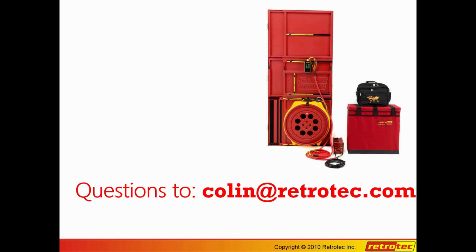Robert Ennis was asking, is it reasonable and acceptable to measure lower leakage area in a room that does not have a suspended ceiling but does have leakage points positioned above the required protection height? There is a thing that we can do, called a leak audit, where we can, let's say, measure 10 square feet of leakage, and if we can show that 9 square feet is above the ceiling, then we can say the below-ceiling leakage area is 1 square foot.